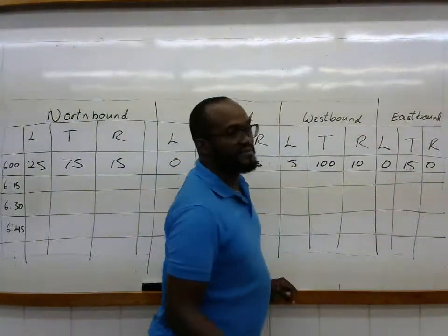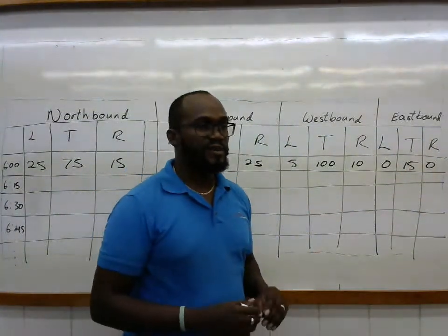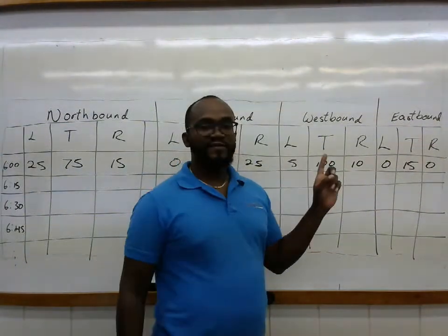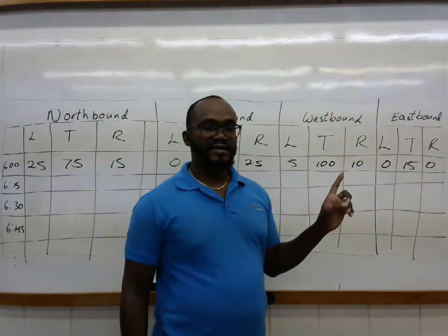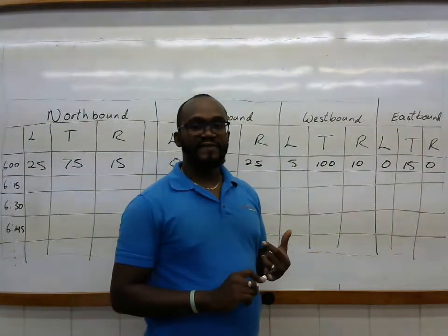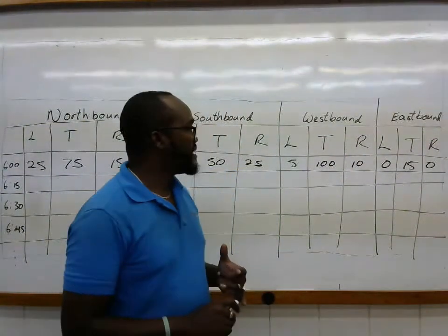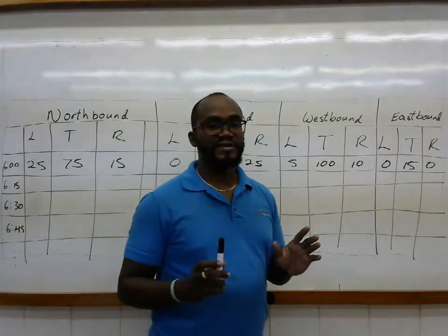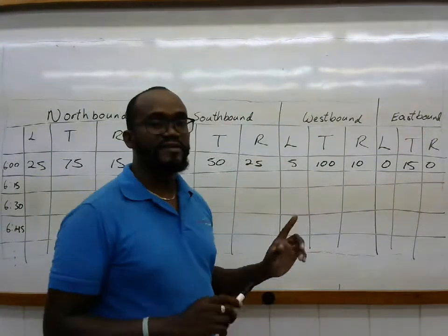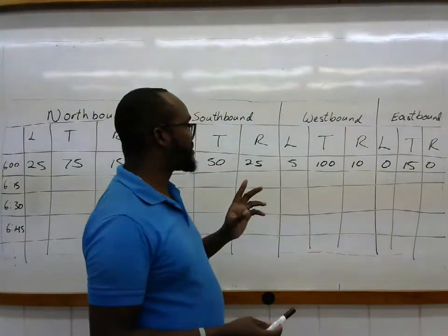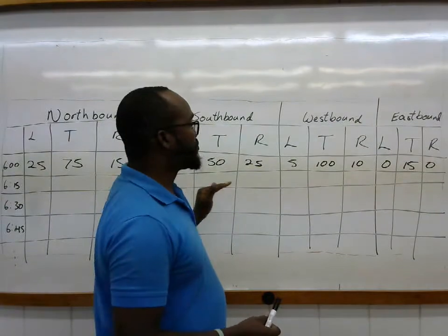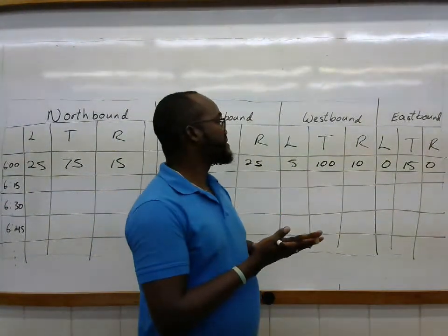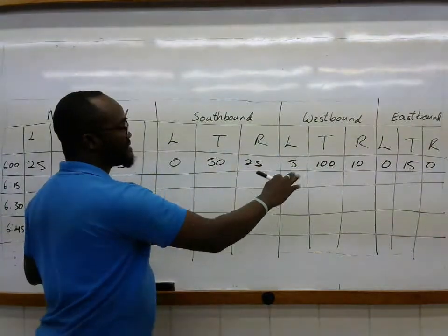Now, it may seem counterintuitive initially, but remember from the saturation flow rate computation, the effect of the heavy vehicles and mixing classes is taken care of by the heavy vehicle factor, that's FHV. So don't worry about the fact that you'll be combining small vehicles with heavy vehicles and so on. That is actually taken care of in another part of the computation. So it's important to remember though, that to work out the peak hour, you must combine all 6 of the tables and then sum horizontally.